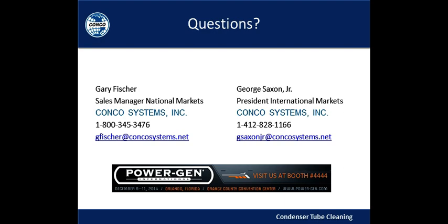And really, there are 2 problems that you have when you have fouling. You have a loss of heat transfer, and you can have under-deposit corrosion. That fouling is detrimental to the heat transfer, which causes the efficiency of the steam condensing unit to fail, resulting in a lower vacuum or a higher pressure, and thus a less efficient turbine operation. So the cleanliness of that condenser leads to how effective that turbine can operate.